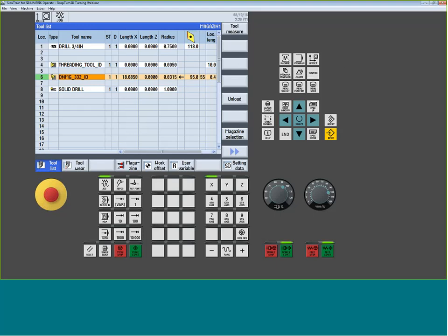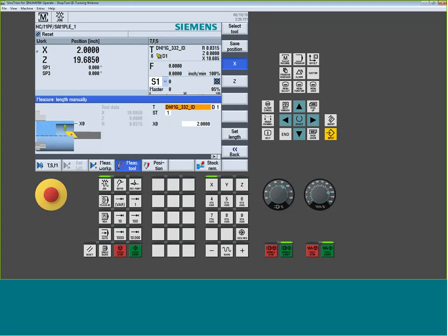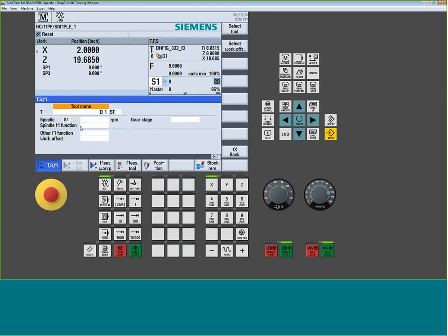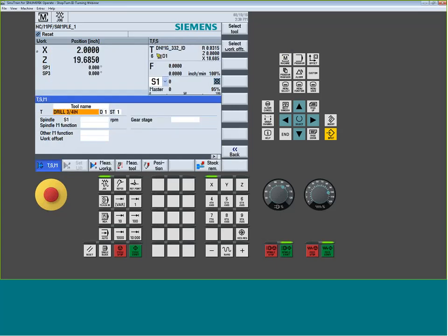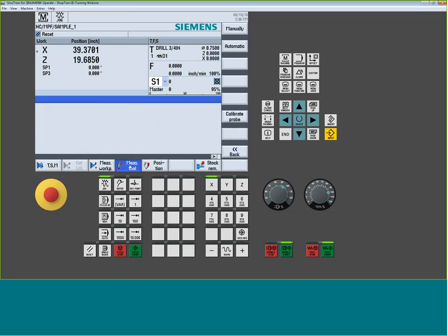Okay. Now, let's start to talk about the drill, because I do want to kind of go through this process, this step. So if we select the drill, and we can select the three-corners drill for argument's sake, it doesn't really matter which one we use. Both are going to respond the same way. You'll notice when I go to the measure tool, on the X, it's asking me again to bump the side of this tool.